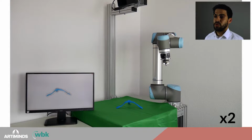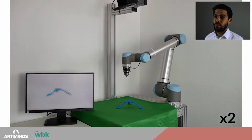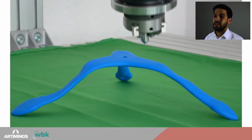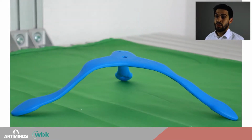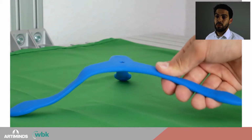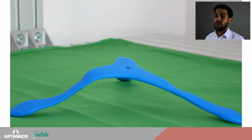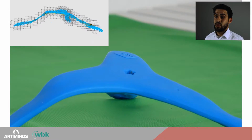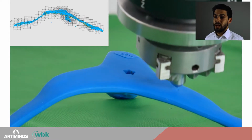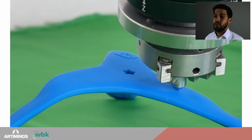Now that the object is moved to a different position, you can see that the user-defined point is again detected very precisely. The average precision we determined in our experiments was 2 millimeters with a relative deformation of 20% with respect to the reference model. In the next step, you can see another deformation being applied, and in the upper corner, a visualization of the converging algorithm. Once the deformation is estimated, the robot can begin with the manipulation.